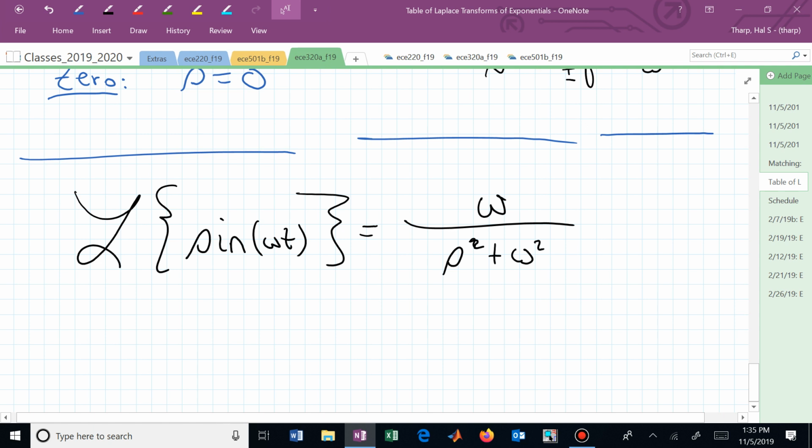That's how some people can say you always have the same number of zeros as you have poles. That's because they're including the zeros at infinity. But here, most of the time, we're just dealing with finite poles and zeros. But if somebody says, what are the zeros at infinity? You can say, well, let me look. Then you're really comparing the order of the numerator with the order of the denominator. In this case, the order of the numerator is 0. The order of the denominator is 2. 2 minus 0, you have actually 2 zeros at infinity.